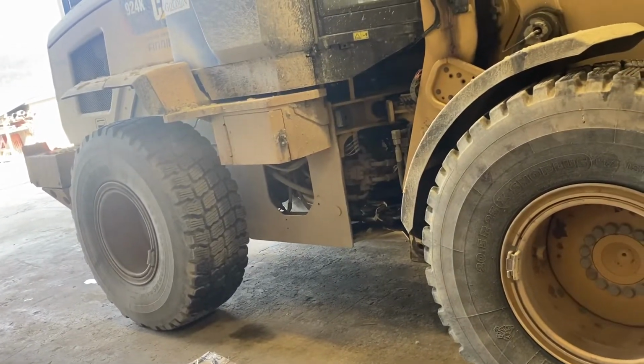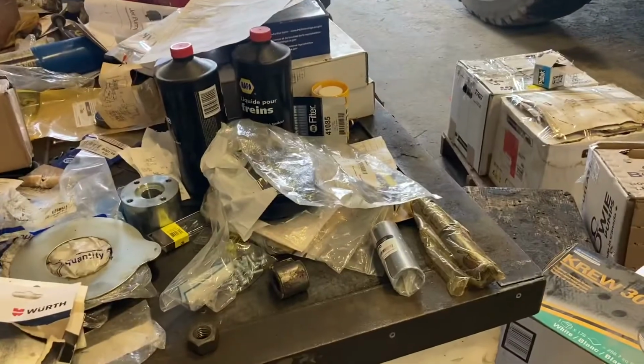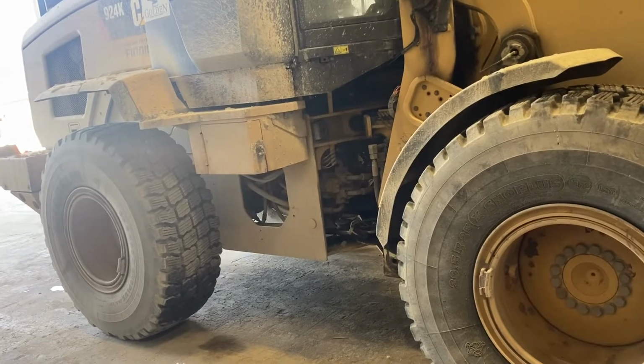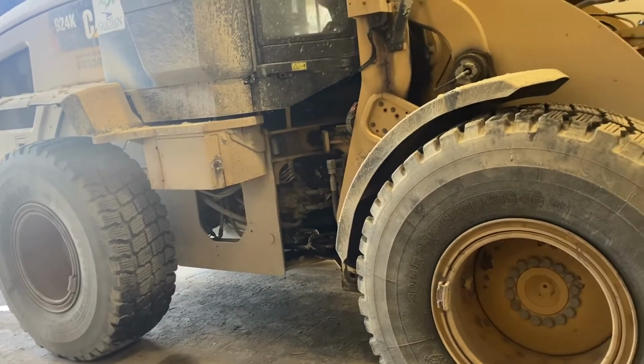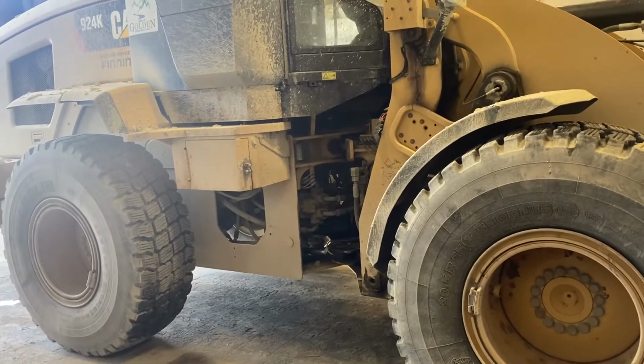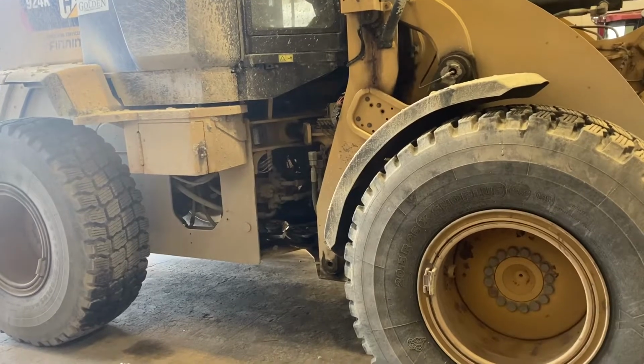Also, the resistance in the coil on the valve, this electrical coil solenoid, is going to go up as the heat raises, of course. So when it's really hot, you might end up, the boom won't come down, or you'll lose your functions. Now, the next day I got in this same machine when the coil was cold and I had all the hydraulic functions.